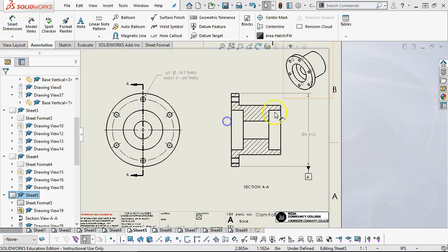And when we apply this dimension, I'm thinking, all right, since this isn't interrupted, I would still think of this as a diametral dimension. So jumping over to the Leaders tab, telling it to switch from radius to diametral, we'll put it into that location. This is going to have that other basis of the shaft. We would have to consider the fits. Is this going to be a plus nothing minus 1, or a plus nothing minus half a thousandth? And then we come over here, and this is a plus 1 minus nothing. Right, so we need to do something with those tolerances.